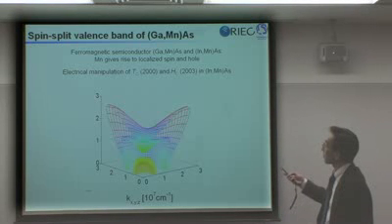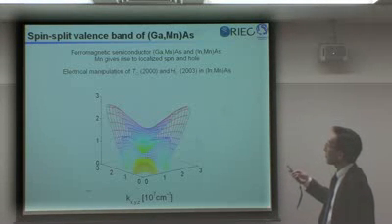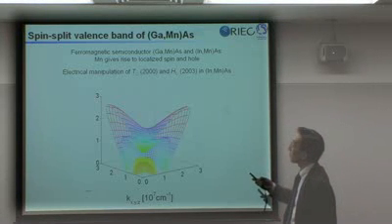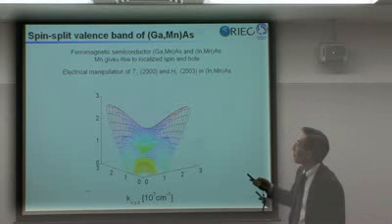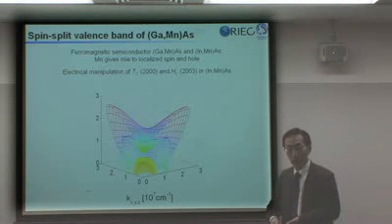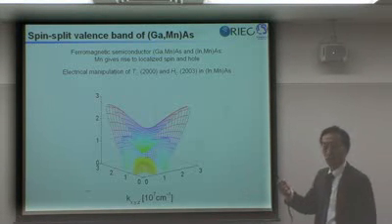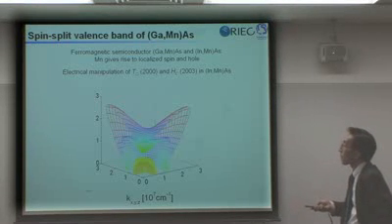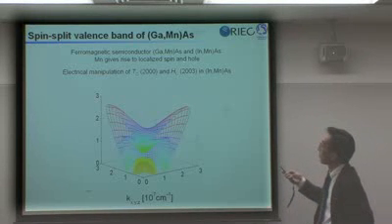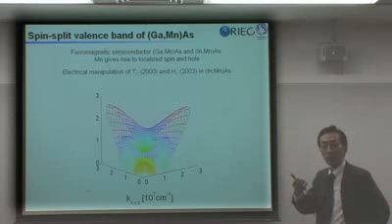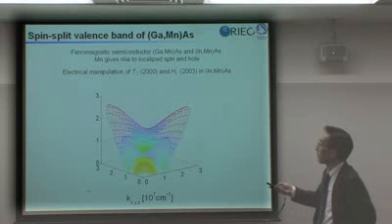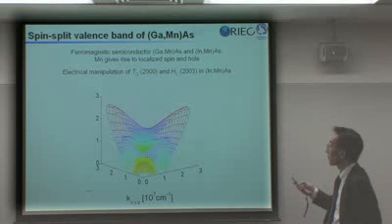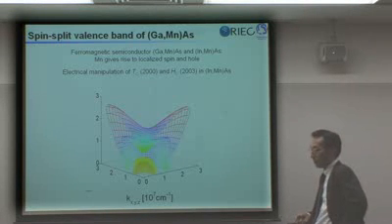The ferromagnetic semiconductor, like gallium arsenide with manganese or indium arsenide with manganese. Here, in those materials, manganese does two things. It gives you localized spins, and it also gives you a hole, because manganese is an acceptor in gallium arsenide or indium arsenide. And interaction between hole and localized spins gives rise to ferromagnetism. And we have shown that we can electrically manipulate transition temperature or coercivity in indium manganese arsenide.